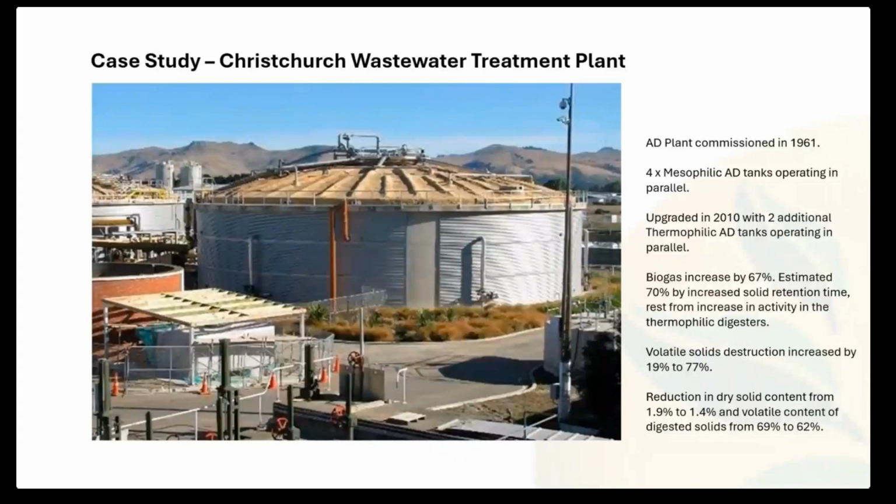And the solids content in the digested solids basically was slightly less, but at the same time, the volatile solids content of digested solids decreased, sorry, from 69% to 62%. Evidence that the organic matter has been degraded more quantitatively.